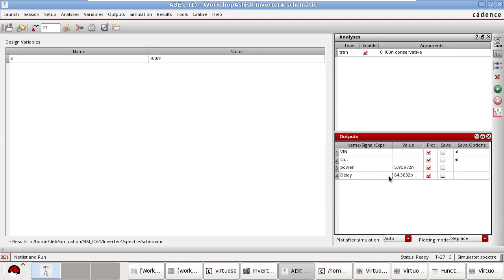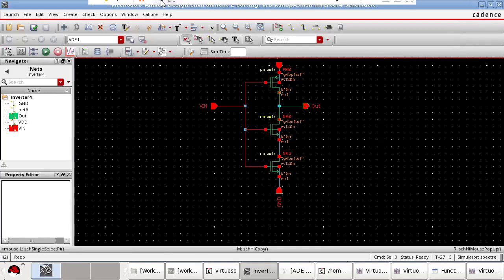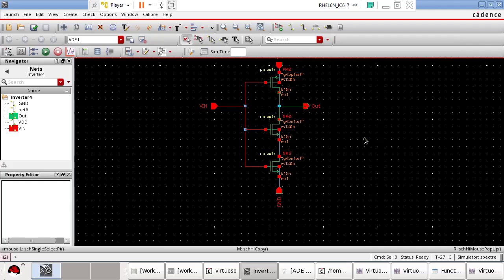Now it is coming in 64 picoseconds. So you have reduced leakage. You have increased the size, you have increased the dynamic power dissipation, you have increased the delay. So this is your impact of using a stacked transistor. Got it? These are all the parameters that you need to take care of when you talk about using any technique. That is why I have calculated all the parameters for you. Now I'll use the other technique for you, which is called using the sleep transistor.